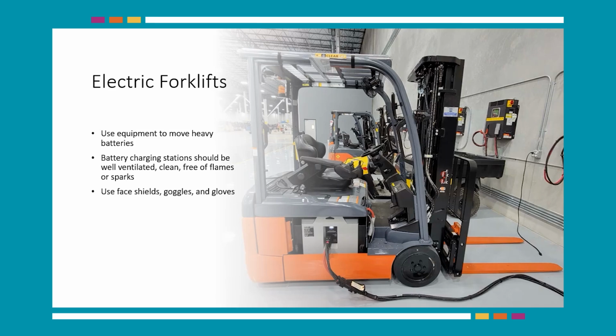The electrolyte in batteries contains sulfuric acid, which is corrosive and can cause chemical burns if it splashes out of refillable batteries. Use face shields, goggles, and gloves to prevent injuries, especially when water is being added after a battery has been charged. Eye wash stations must be located within 25 feet of battery charging stations.